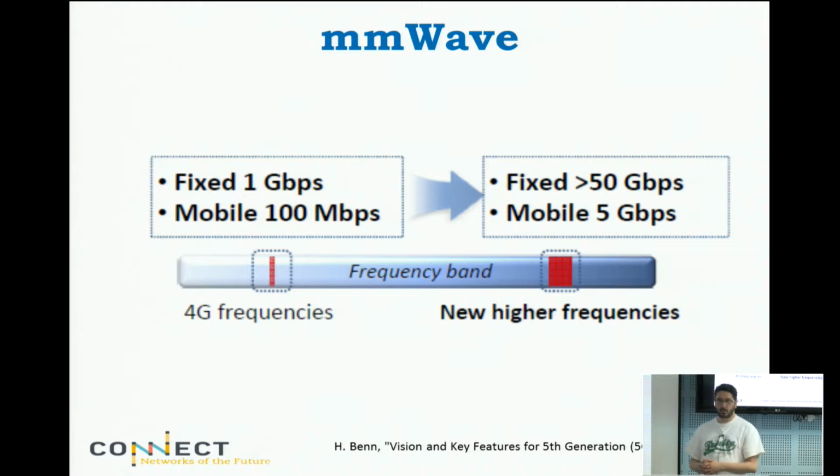What can you do to combat this limited propagation and to still be efficient in your transmission? It's kind of a default assumption that when you have millimeter wave, you have beamforming. Okay, you do have to have some MIMO system doing beamforming, because the limited power you have at the transmitter has to be really well used. So it's not like you can be squandering it like you do at lower frequencies, where it doesn't matter because the signal propagates naturally far. Here you have to be more conservative, right? So you do need to basically transmit directionally.